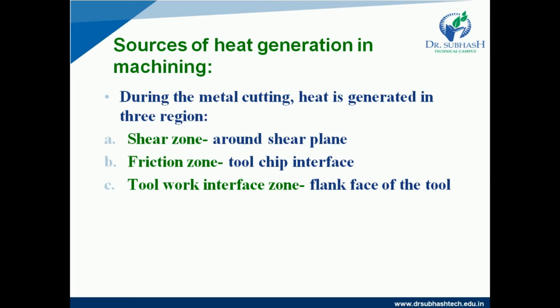Shear zone, that is around the shear plane. Friction zone, that is around the chip tool interface. Third one, tool work interface zone, which is around the flank face of the tool. So mainly there are 3 zones, which are called the sources of the heat generation.